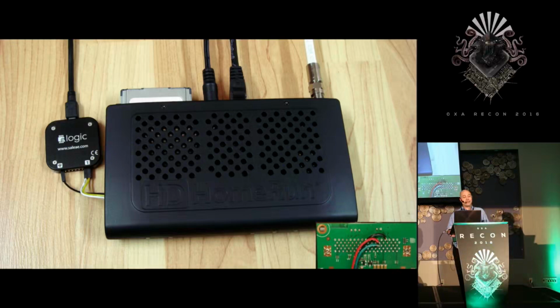Another cable TV adapter is the HD Home Run Prime. It's a network-connected 3-tuner device, and this one has cable card support. The set-top boxes I studied predate cable cards, but newer boxes do use cable cards that support the DC2. With cable card support, that means that the HD Home Run Prime has the tuner and QPSK demodulator to handle the out-of-band channel, so it can pass that data to the cable card. But the HD Home Run doesn't make that out-of-band data available other than via that cable card interface.